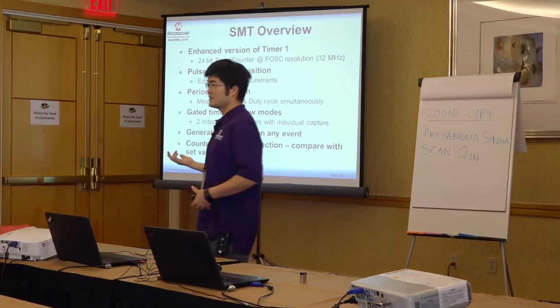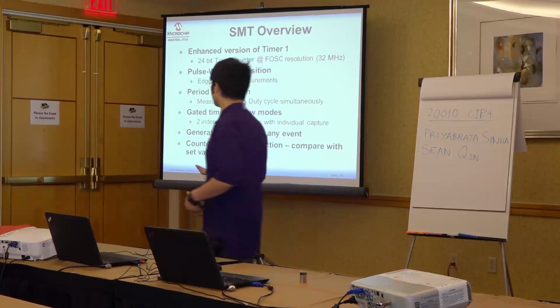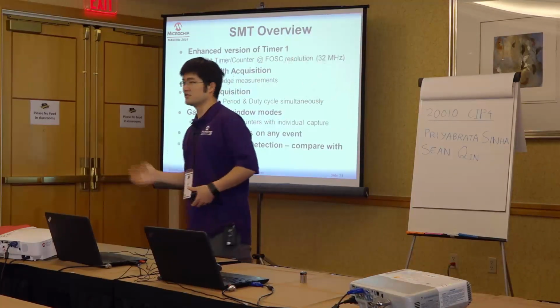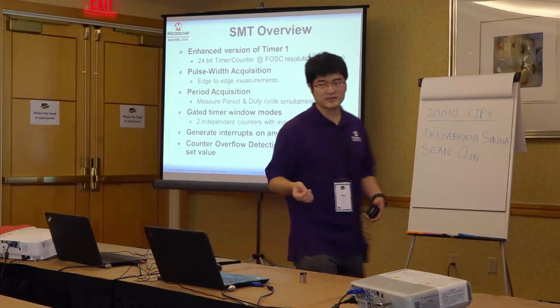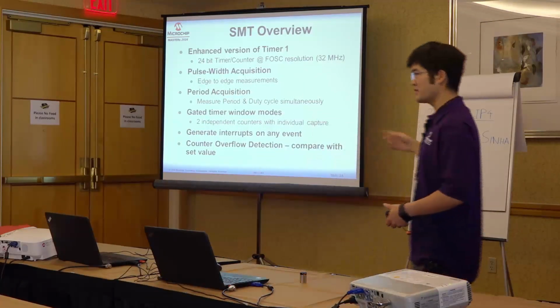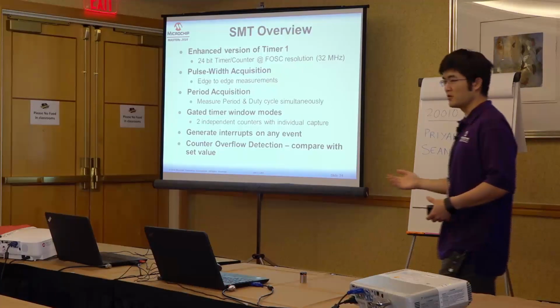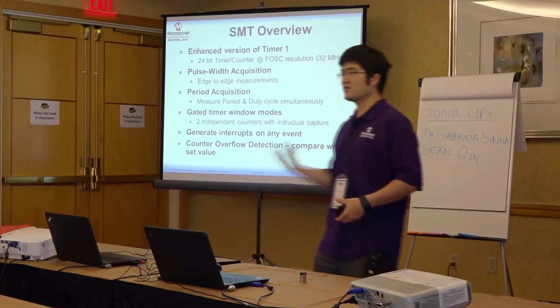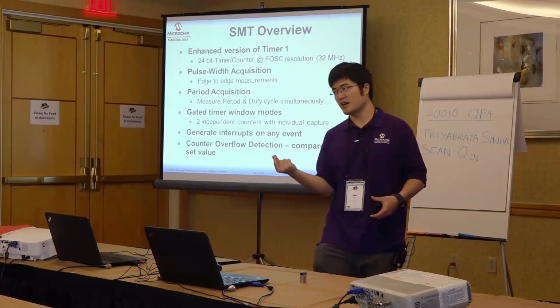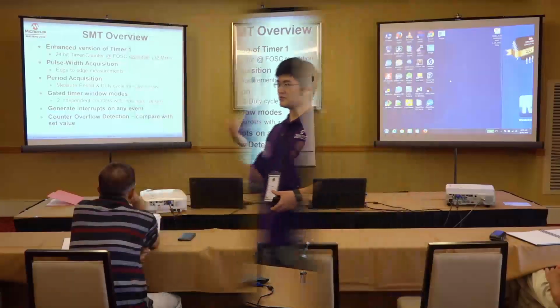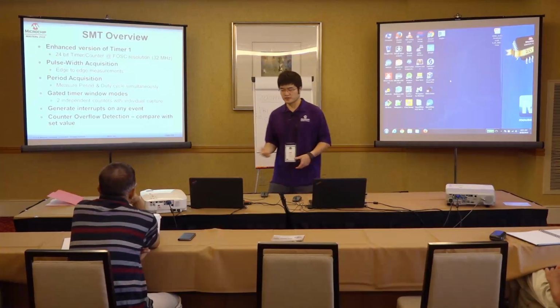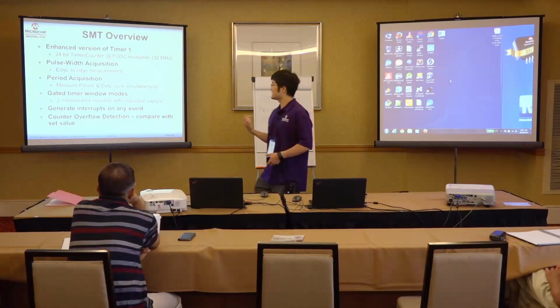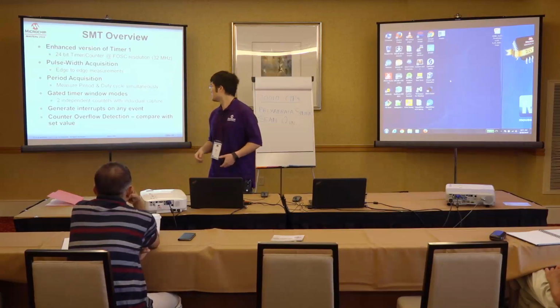In that case, naturally, you will think about using it for period acquisition and duty cycle acquisition. So you have a PWM wave coming in, you can use SMT, and it will capture those events and give you the number of counts between them, which naturally gives you the duty cycle and your period. It also has gated timer window modes.